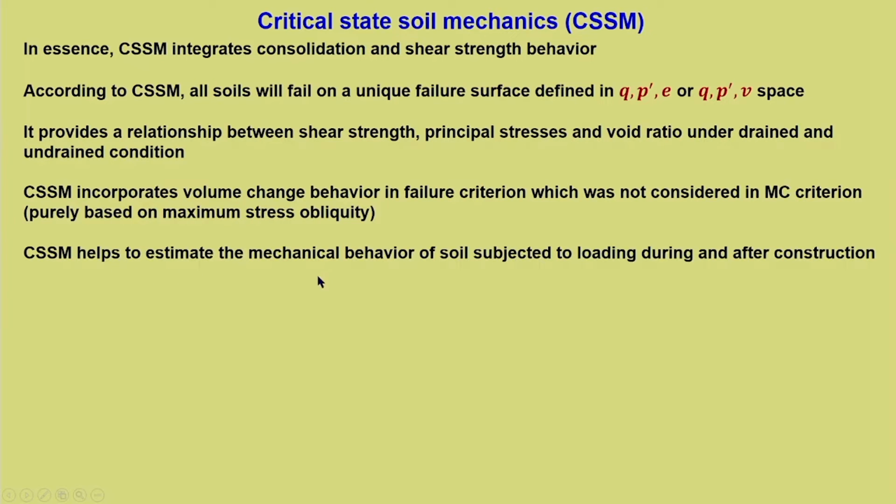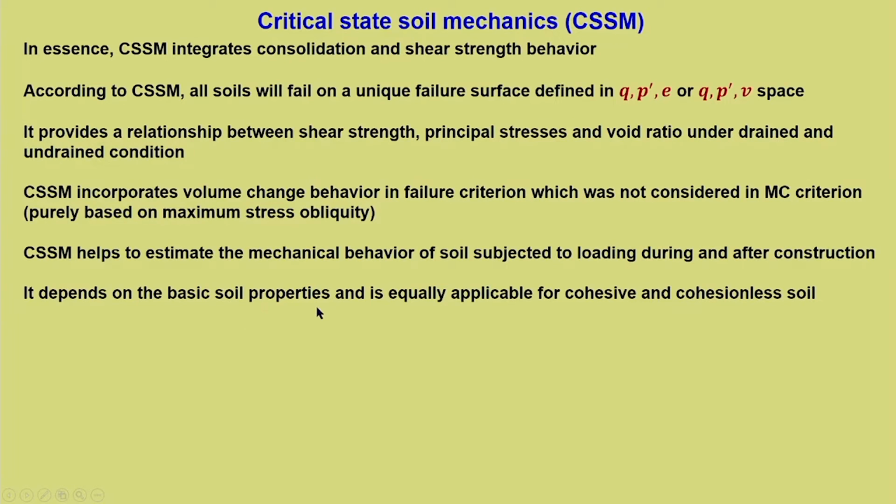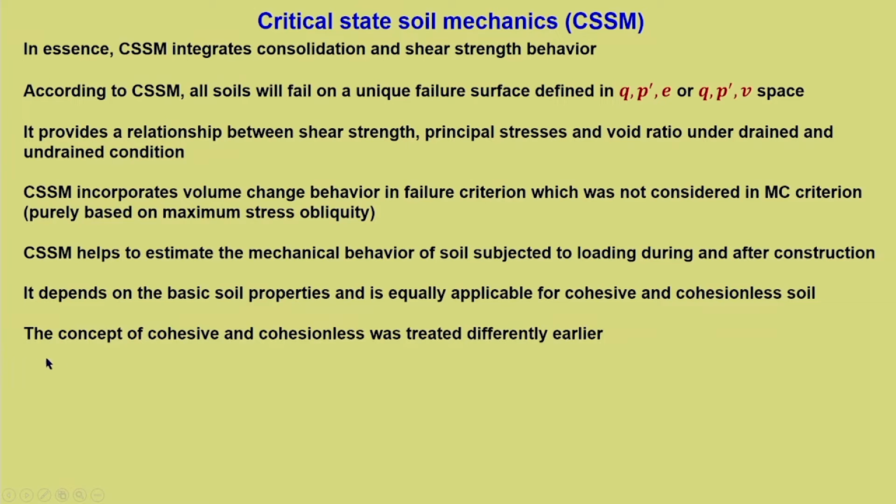CSSM helps to estimate the mechanical behavior of soil subjected to loading during and after construction. Later you will see that, based on this framework, you can predict the behavior in drained, undrained conditions or with respect to stress history. It essentially depends on basic soil properties, and it is equally applicable for cohesive and cohesionless soil. If you remember, in the earlier lectures the concepts of cohesive and cohesionless were treated differently.